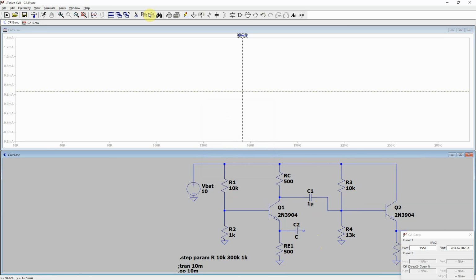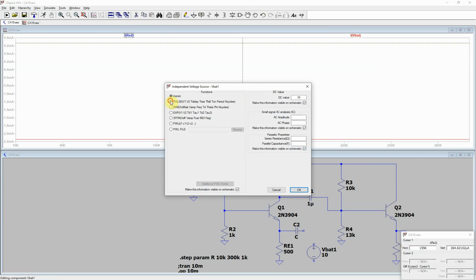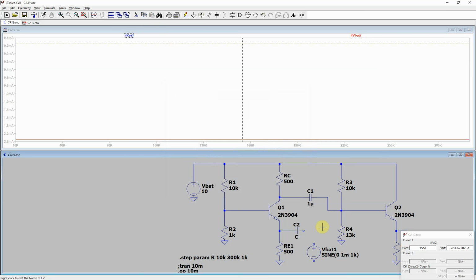We're going to put in our input source here, and then we're going to connect that up. Now this one is going to see like 50 ohms this direction and 0 this, so this one has to be a lot bigger of a capacitor.